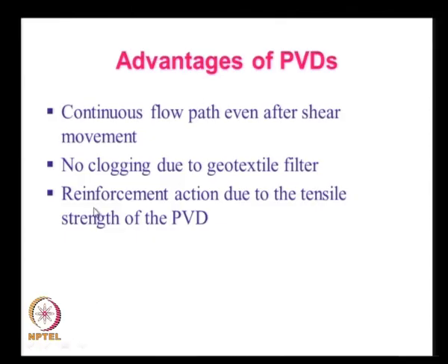And because each of these PVDs has some tensile strength, they also give some reinforcement action because of the tensile strength of the individual PVD, because typically these are installed at a spacing of about 1 to 3 meters center to center, and so we can expect a very large number of these PVDs within a unit area that can provide some tensile resistance either from lateral deformations or from horizontal deformations.